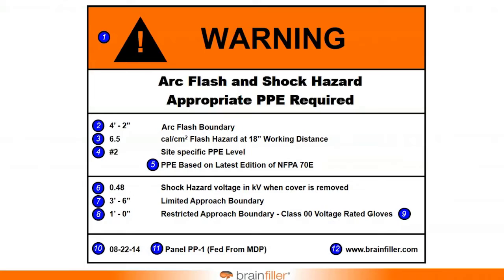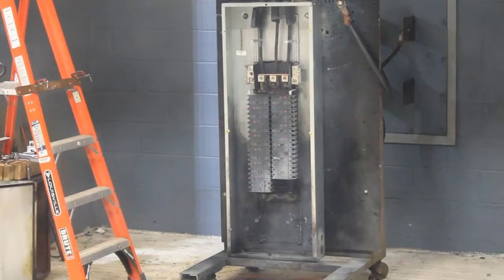So the arc flash labeling is really to provide you information that you need to identify the shock hazard and the arc flash hazard. And so, for example, this was a test setup that I did in the lab a couple years ago, and you could see up at the top I have a solid copper rod. And so this rod is to simulate, what if you drop an uninsulated tool and it hits the bus? Well, the arc flash label would give you some kind of an indication, A, as to what the shock hazard is, that's part of it, but B, what kind of arc-rated arc flash protection would you need? So let's take a look at what happens.